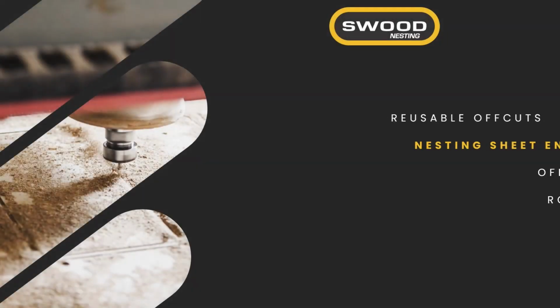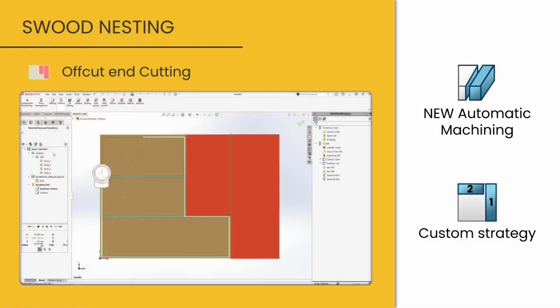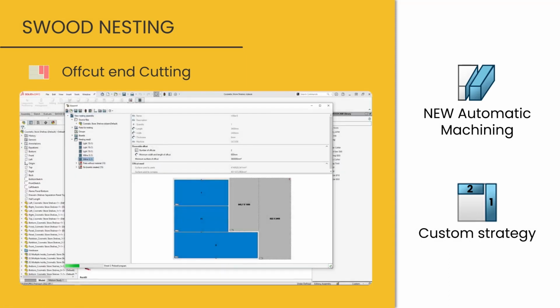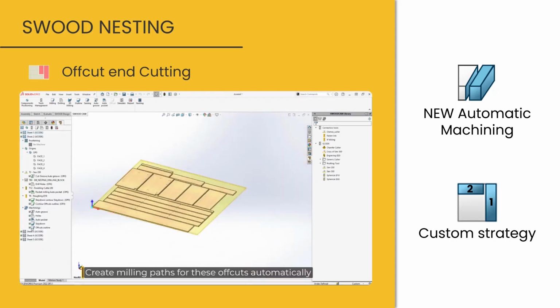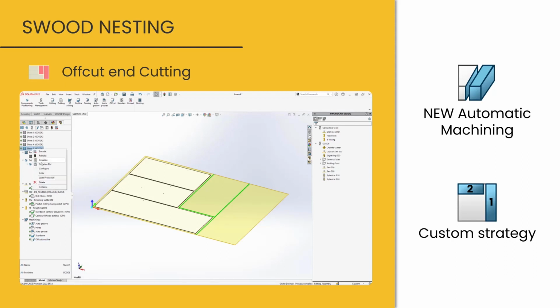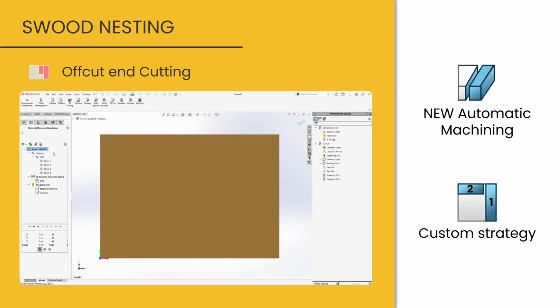When the offcuts are detected, SWOOD has to cut them with this new operation, nesting sheet and cutting. After validating the nesting results, the machining insertion feature in SWOOD-CAM programs, an update of SWOOD 2022, detects all the offcuts in the nesting sheet. The new automatic machining feature enables a contour operation based on a specific strategy. The video shows that the stay-down contour operation completes the sheet by cutting the offcut in red.